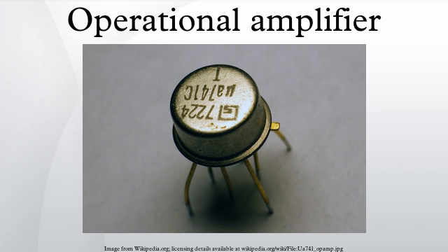Thus, the quiescent currents are pairwise matched in Q1/Q2, Q3/Q4, Q5/Q6, and Q7/Q15. Voltage amplifier. Quiescent currents in Q16 and Q19 are set by the current mirror Q12/Q13, which is running at approximately 1 mA. Through some mechanism, the collector current in Q19 tracks that standing current.